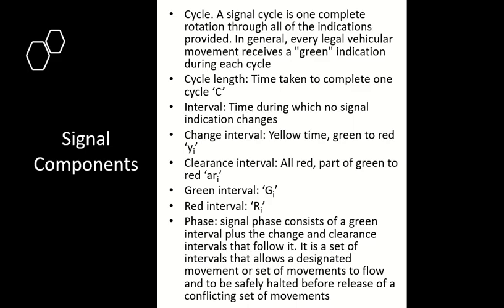So in most cases, when you cross during yellow, before you reach the other side, before you clear the intersection, the signal behind you will become red. If the next one immediately becomes green, it is risky for you and the other driver. He may look at the green and enter while you are already there. So we give some gap between the red of the first phase and the green of the next phase. This gap is called all red. Your signal is red and the next one is still not green, so it's all red. Another name for all red is clearance interval.